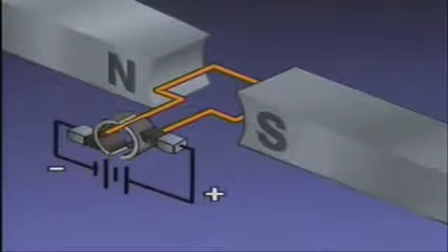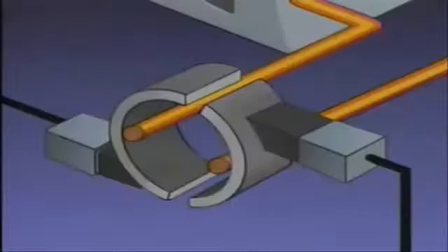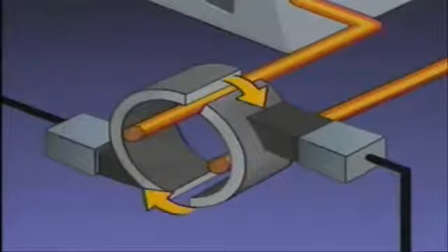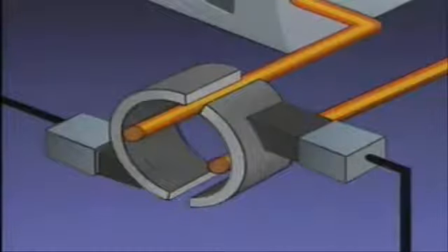The brushes are connected to the DC power source. The commutator is mounted on the end of the armature so that it can make sliding contact with the brushes. The commutator is not a solid ring. Instead, it consists of conducting segments that are separated from each other.